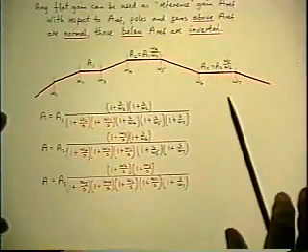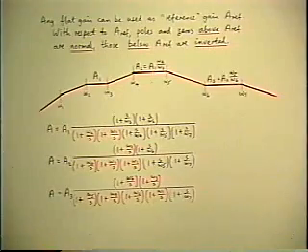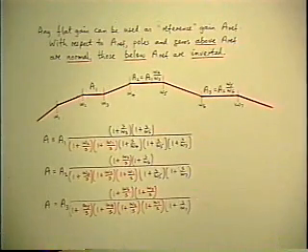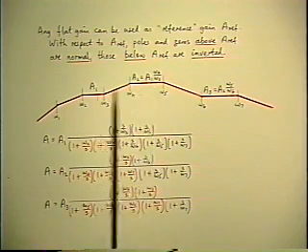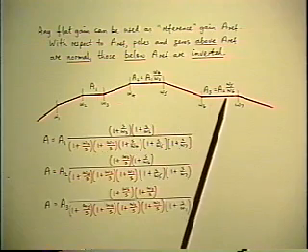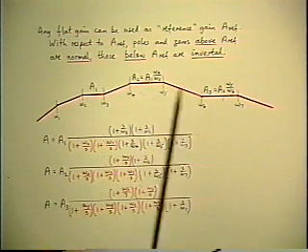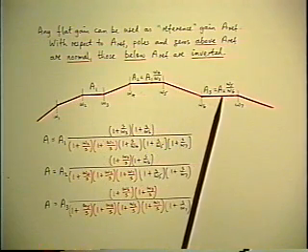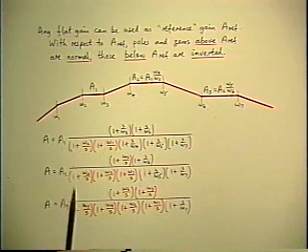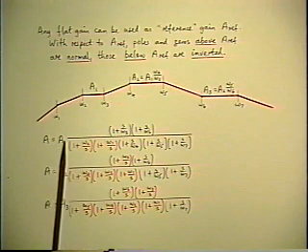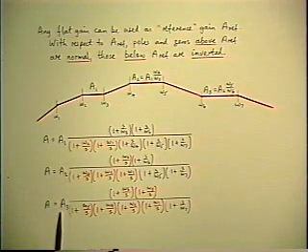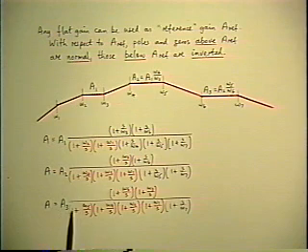And here's a little more complicated case just to illustrate that. There are three flat gains. I've already written on the picture the necessary relationships between them, employing the gain bandwidth trade-off ratio. And here are three different versions of how to write the factored pole zero form, choosing each of the flat gains in succession as the reference.